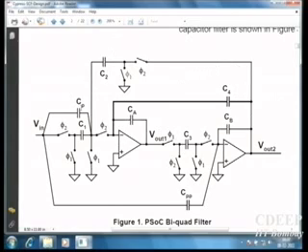C2 and CP. No, this is because of switch sharing. We have here on the left side there should be two phi 1, phi 2. We remove them because already C1 has phi 2, phi 1. So this we have removed. In fact, they have also removed phi 2, phi 1. That is correct.